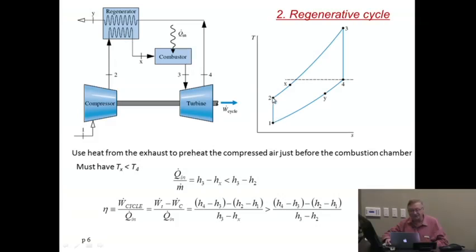So we will get the air from 2 to X warm by using air temperature and enthalpy that comes from point number 4 and having this heat exchanger here between X and that. That means that then the fuel is only needed to get the enthalpy from X to 3. In other words, you need to fuel only the part X to 3 of the cycle.